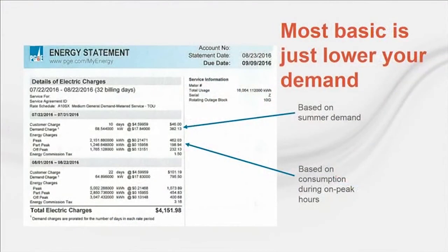As an example, SoCal Edison, the utility covering the southern region of California, as the name may suggest, charges their customers who use between 500 and 1,000 kilowatts $37.12 per kilowatt in the summer months, as you can see on the sample invoice. Under this rate structure, the demand to run chillers and pumps for an 800-ton chiller would cost nearly $25,000 during summer months. Local utilities are also offering programs for end users to participate in demand response.